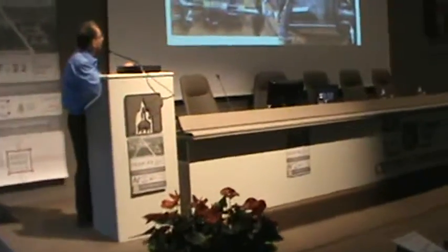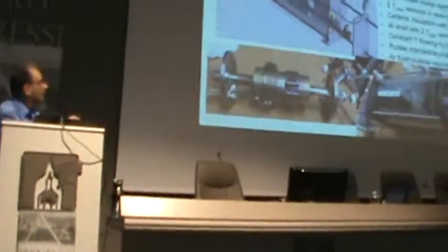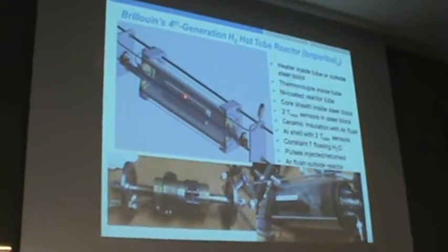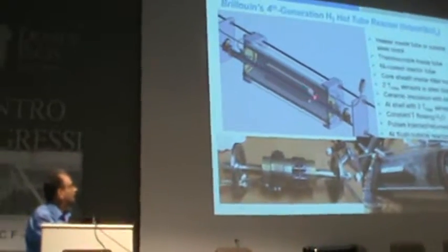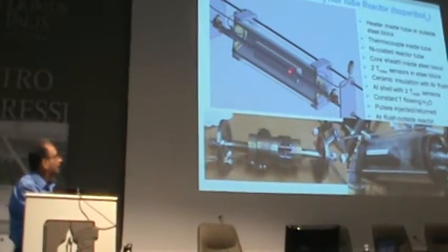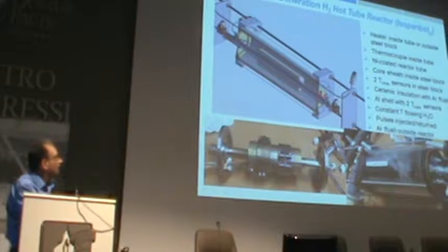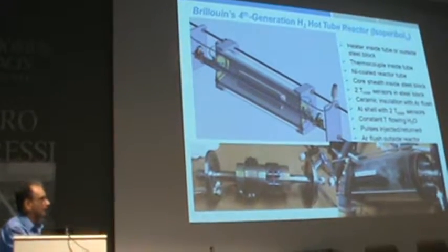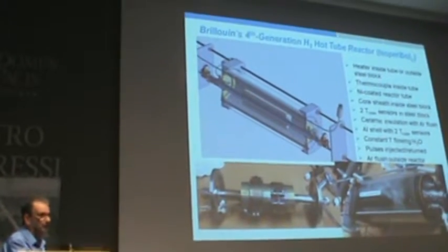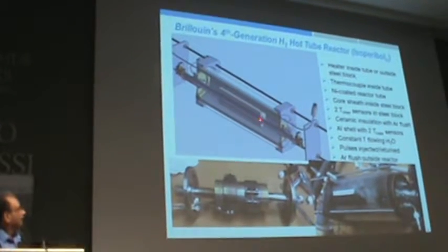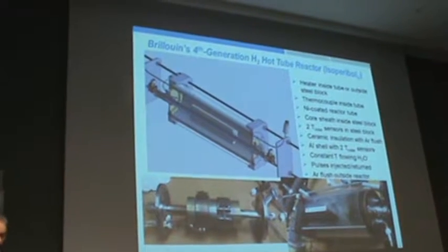There are temperature sensors. There is a thermocouple in the middle of the heater, in the middle of the reactor tube. There's a thermocouple out here. There's a thermocouple coming in here. Outside of this heat spreader is insulation. And then there's another aluminum cylinder with a couple of thermocouples in that. And then an acrylic cylinder around the aluminum cylinder completes the mass flow calorimeter. The temperatures in the mass flow calorimeter are measured with RTDs and flow rates with standard flow controllers.